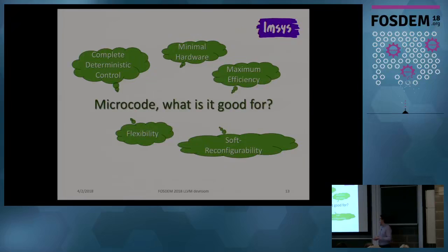And also, we believe that microcoding the complex operations helps improve performance. In this case, the whole complex operation is in microcode, and otherwise, if we would have only a simple RISC instruction set, then the same operation would take a sequence of assembly instructions, which would take extra time to decode all of the instructions and so on and so forth.